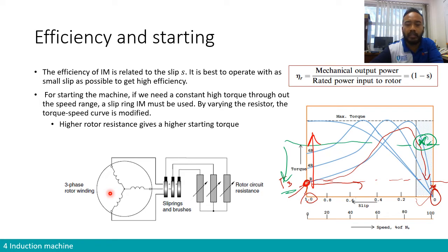For a machine that was designed for a specific load, you can basically choose a machine where the starting torque is much higher than the load. But for a machine that's going to be used for different starting loads, it is better to have this control on the starting torque with the integration of slip rings and brushes, with the integration of a variable rotor resistor.